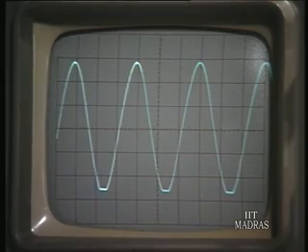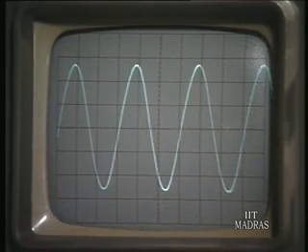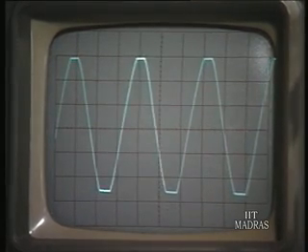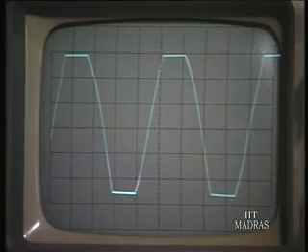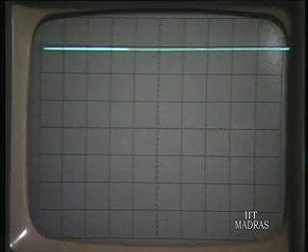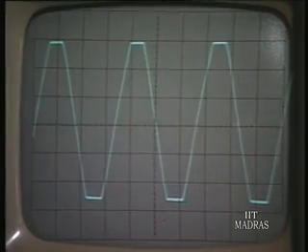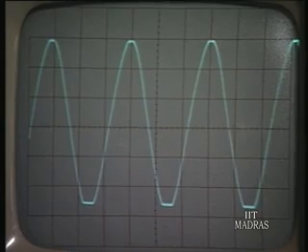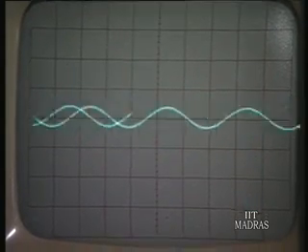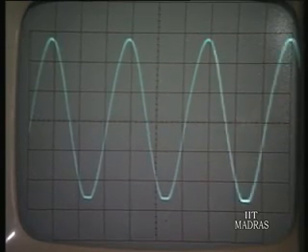Yes. Now it is almost going to saturation, you can see. There is no control over the amplitude of oscillation, it will go to almost plus minus the supply voltage. See, it has gone almost up to plus minus. She has introduced too much positive feedback here. Now, it has gone to saturation altogether, too much positive feedback. And this is clearly demonstrating the effect of too much positive feedback. You have to introduce just enough positive feedback to get rid of the negative feedback, then only it will give you a perfect sinusoid. Otherwise, it will be distorted.